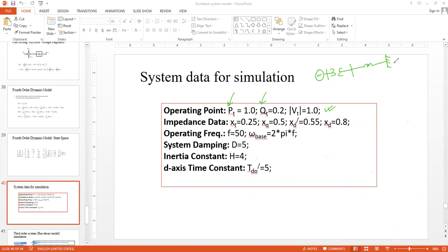And this is the infinite bus. So this is your VB. If you want, you can omit the transformer for the time being, because ultimately your transformer and transmission line would both be series connected. So you can also include this XT within this XL and vice versa, and make it only a series element between this bus and this infinite bus.